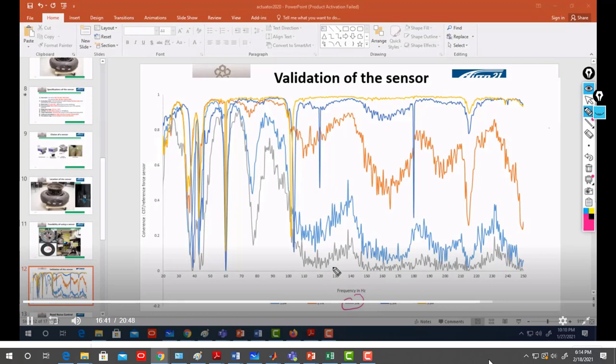Therefore, if you want to use that sensor on a good road profile, we need to improve the sensitivity of the sensor. If our road profile is not good enough, assuming 25 Newton road noise, then I can use the sensor. So I'm assuming now I have a bad road profile, I'm applying 25 Newton, and I will check in the next slides the control performance when applying 25 Newton.